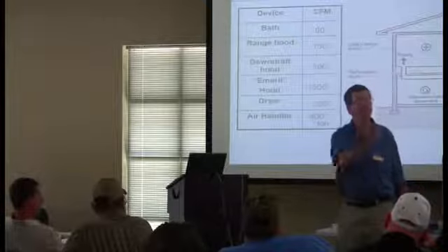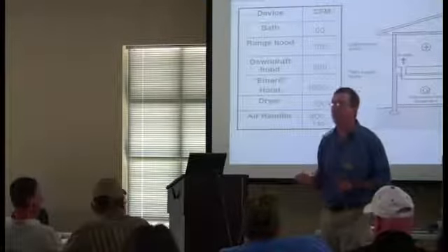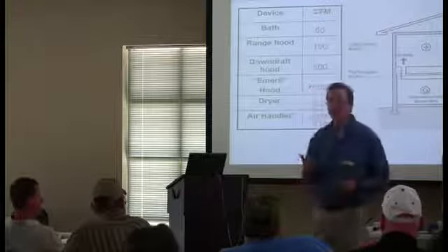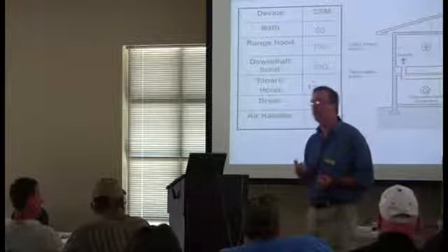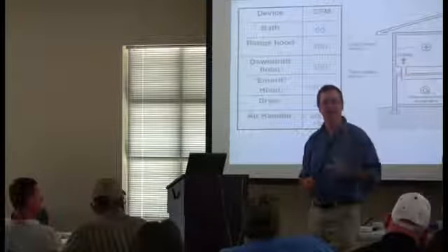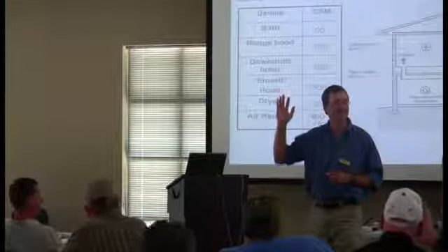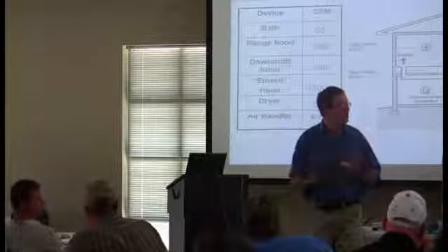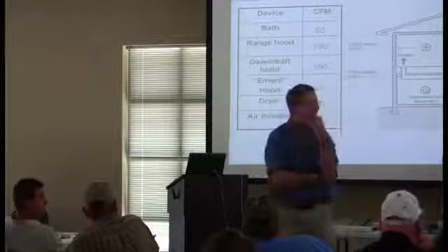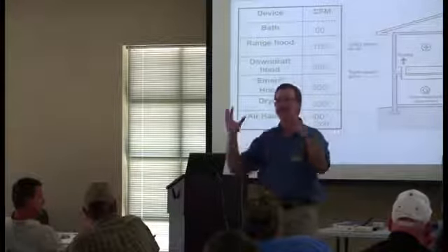Well, duct leakage is a huge one. So there's actually two things. One is duct leakage. The other is return path. So maybe let's do return path first. I want you to envision a home. See if you've ever seen such a home that has one return duct. Anybody ever been in a house with one return duct? Is that a rare occurrence? No. Very common to find one return. Where is it located? Right in the central hallway, right? And that works great.